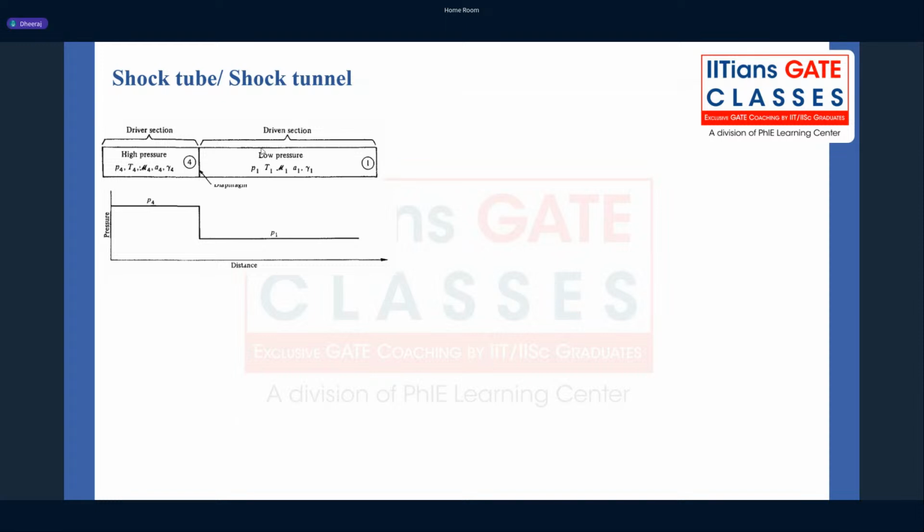mostly we are interested in the shock tube or the shock tunnel problem. A shock tube is basically an almost constant diameter tube, and it is divided by a diaphragm. So this is my diaphragm. This diaphragm can be anything.